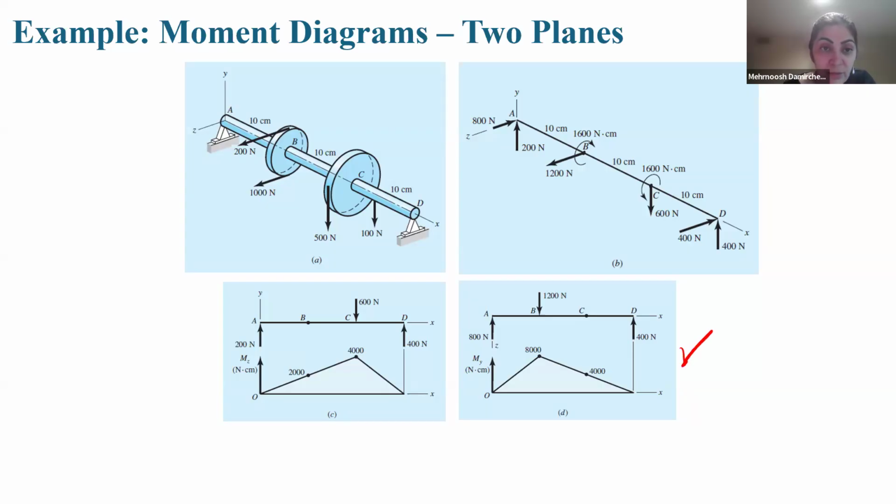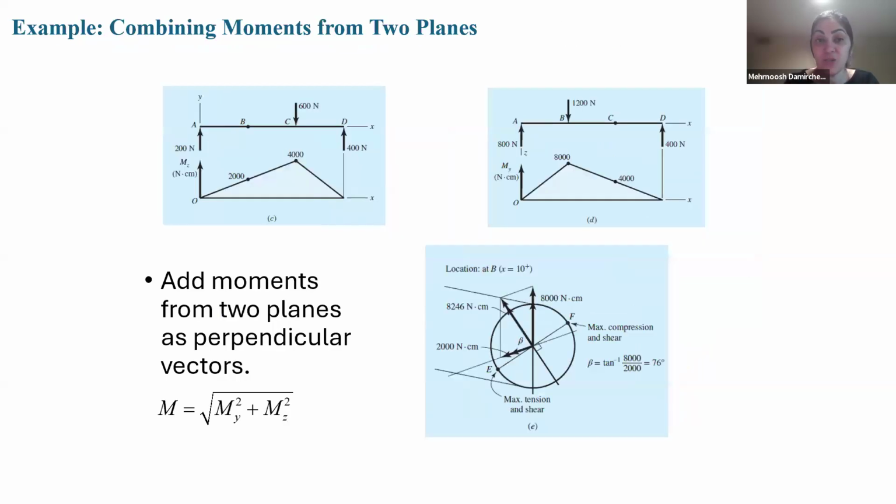And another 500 and 100, it is in Y direction. That you see the equivalent is, for example, 600, 2000, 1000 here, 1200. And we have the support here, but the reactions of the support is not only in Y direction, it is in Z direction too. Here you see the support reactions in Y, support reaction in Z. So it is bending moment in Y direction, it is bending moment in Z directions.